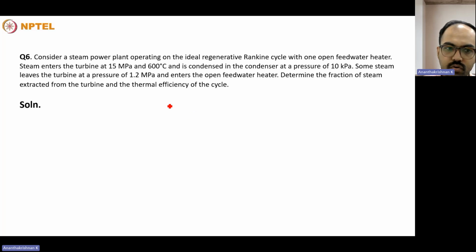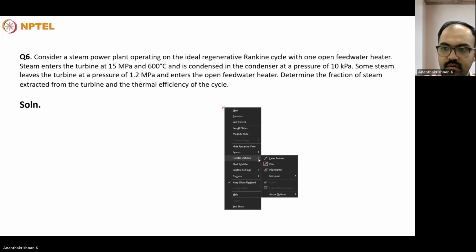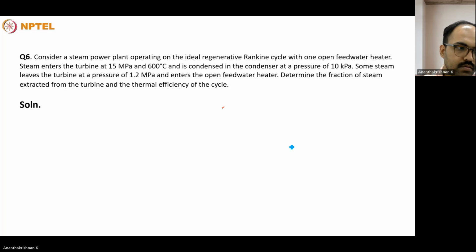So we will try to draw the schematic of the regenerative Rankine cycle with open feed water heater. So we start from the low pressure pump, sorry, on a TS plane.